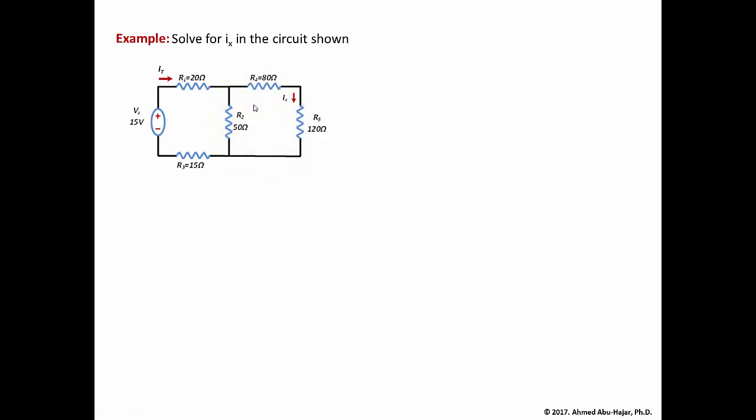The first thing we're going to do is combine those two resistors into one equivalent resistance. To do that, basically you're going to add them up. Those two resistors are going to have this equivalent resistance, which is basically the sum of the two resistors. We're going to call this resistor R equivalent 1. Then R equivalent 1 will equal the 120 ohms plus the 80 ohms, this resistor plus that resistor, which is 200 ohms.